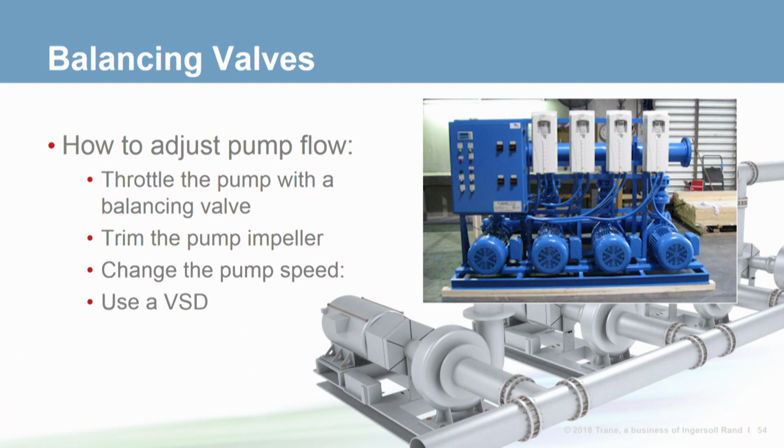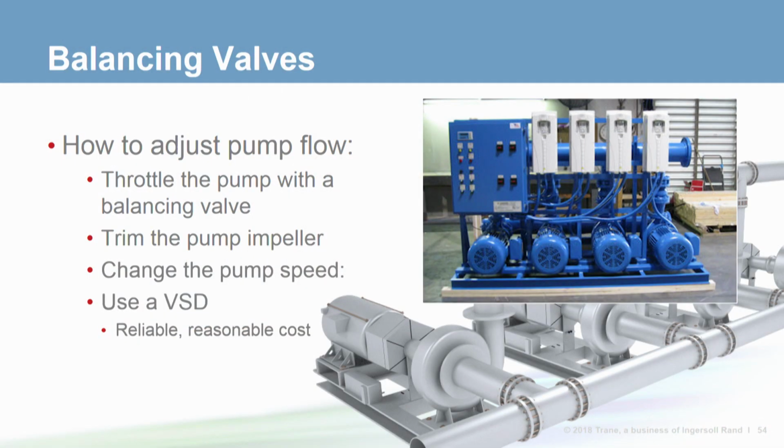The reality is that variable speed drives have come a long way since their introduction. In the past 10 years or so, they've become much more reliable and their costs have come way down. For today's jobs, it's probably fairly easy to justify the cost of a variable speed drive compared to the energy penalty of having a permanent pressure drop included in the system, as is the case with a balancing valve. One final caution, however: take care when applying a variable speed drive to an existing motor. Consult the drive and motor manufacturers to ensure compatibility. If not compatible, the motor may need to be replaced.